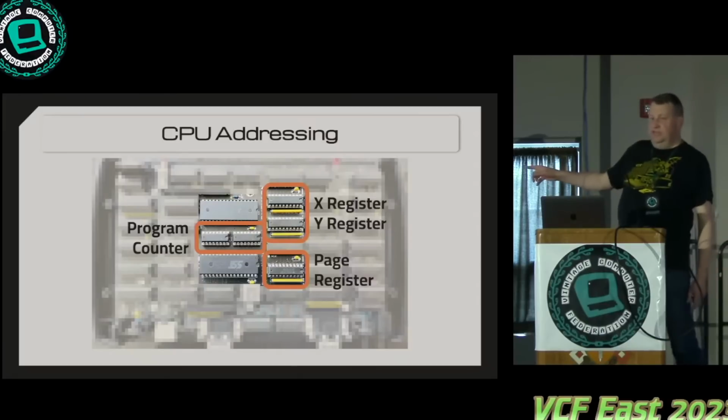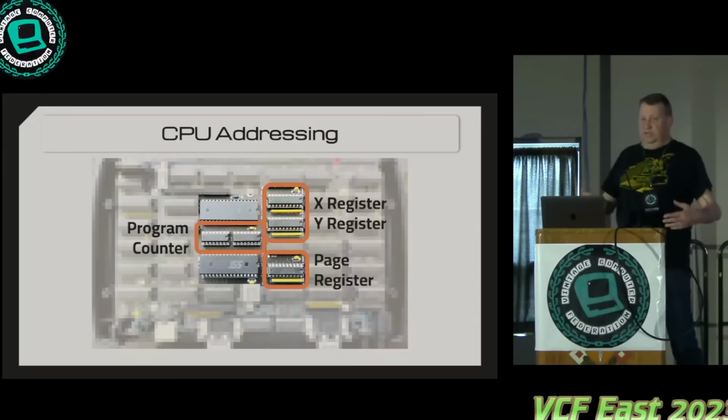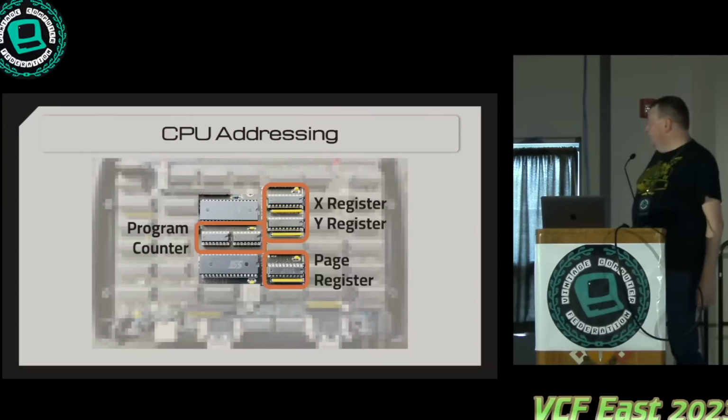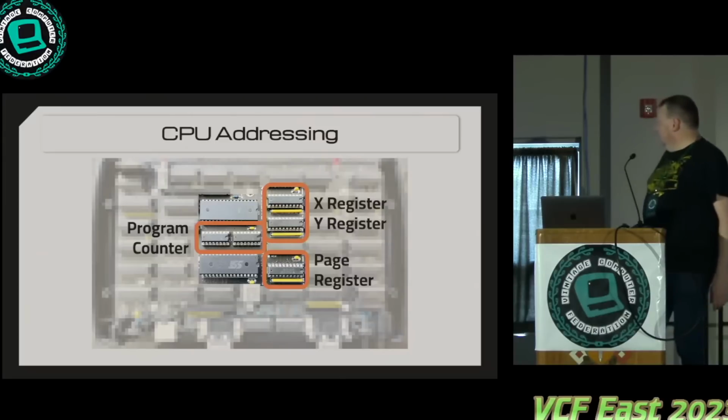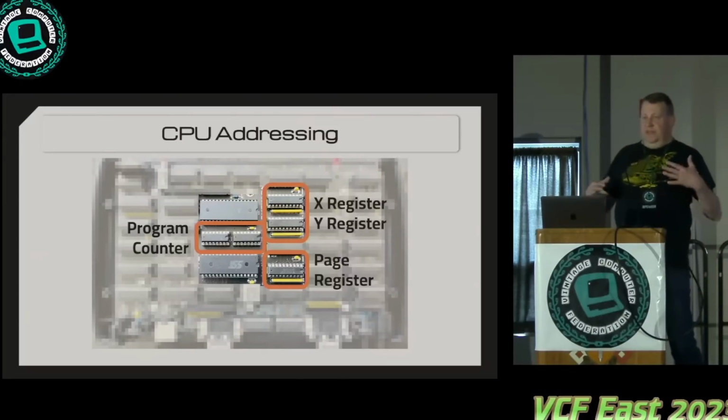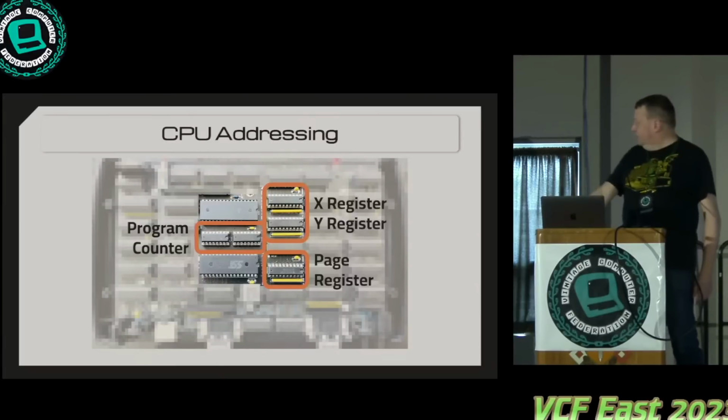That's used with the page register. So during boot, it just doesn't turn on the page register, and it goes to FF, and that's where the boot code starts. And then there's a 0 page we'll get into later, but that's done the same way by pulling it to FF instead of pulling it down to 0. This is like a really cheap way of doing it.